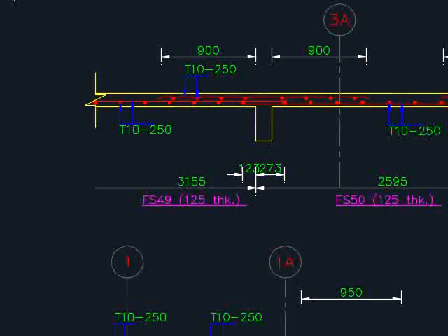You need to be careful to avoid confusions, especially when it is not properly done. These mispositions of the reinforcement bar in terms of the main and the secondary may seem minor. However, in terms of the calculation steps, the effective depth of the slab, which is d, varies, and this can lead to a significant difference in terms of the bending moment capacity of the slab.